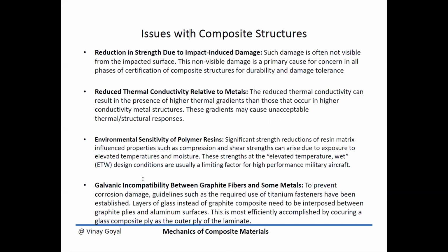And so you've got to use some sort of damage indicator, and that can be paint, cork, or even protective devices to ensure that we don't introduce damage during the processing of the hardware, that you have insights into the hardware, that you're not missing something during the processing that can expose the structure to various levels of impact damage that could be detrimental to the strength of the structure when it's actually put in service.